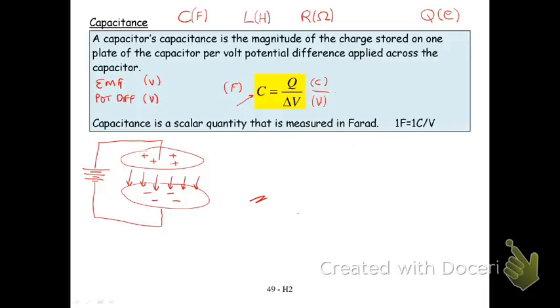It's a bit like the water pump creates a water pressure difference, and the straws support a water pressure difference. The straws don't create pressure, you need a water pump for it. So, although it's all measured in voltage, we refer to the voltage that we're creating as the EMF, and the voltage that we're dropping across our components as the potential difference, but it's all measured in volts.